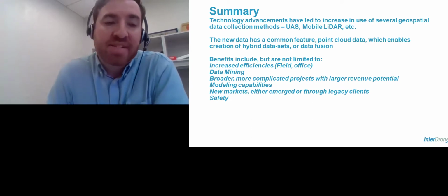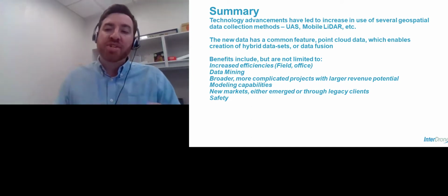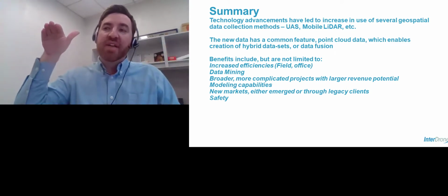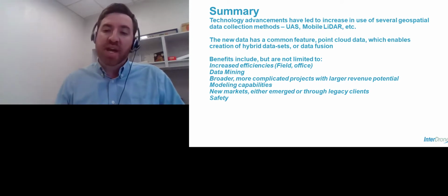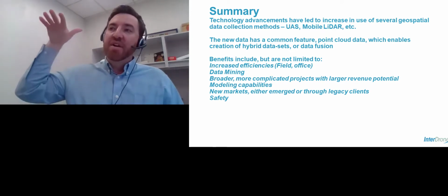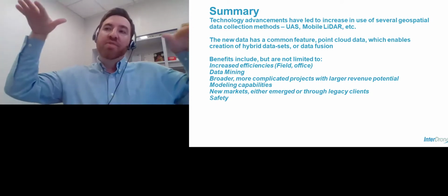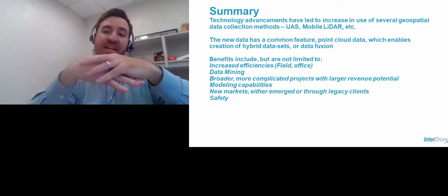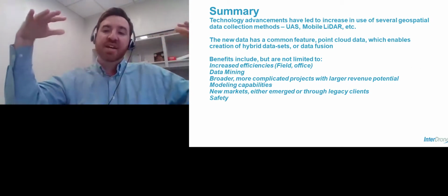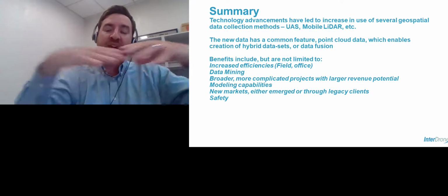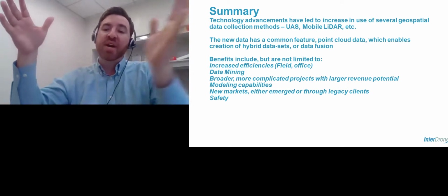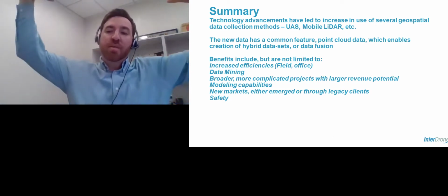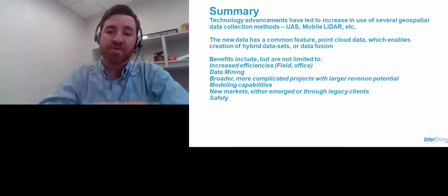A few of them have mission planning that helps you automate your flights: you give them the road location, you give them a buffer, and they help you build out where the drone needs to be at different altitudes to get enough overlap, because that's the key. I didn't get into that today, but the key is that your imagery has enough overlap that it can all stitch together properly. So we were able to fly over, let's say, the sidewalks on both sides of the road, and since we were up at a good altitude, we had plenty of overlap to build one data set.